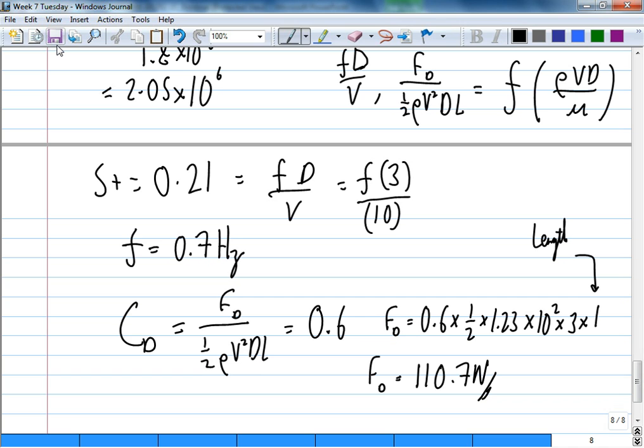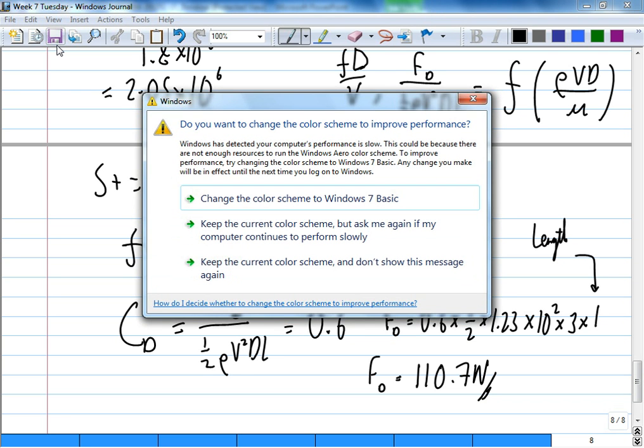Okay. So from about 1,000 all the way to about 10 million. That's the drag coefficient if you have a plate, cylinder, and so on. We'll talk a bit more about this when we do the next chapter on external flow. But suffice to say, you'll be using a lot of this. Sometimes they come in the form of a graph. Sometimes they come in the form of an equation, like a curve fit equation. CD equals something, something, Re to the power something. So don't panic. Either one can be used.